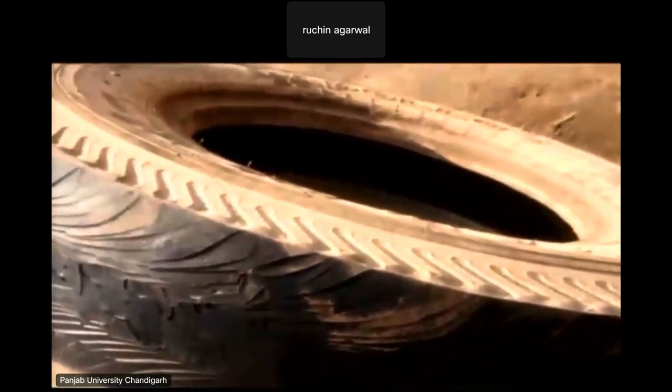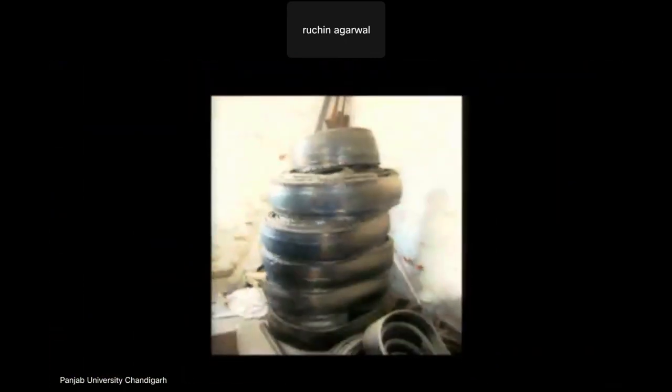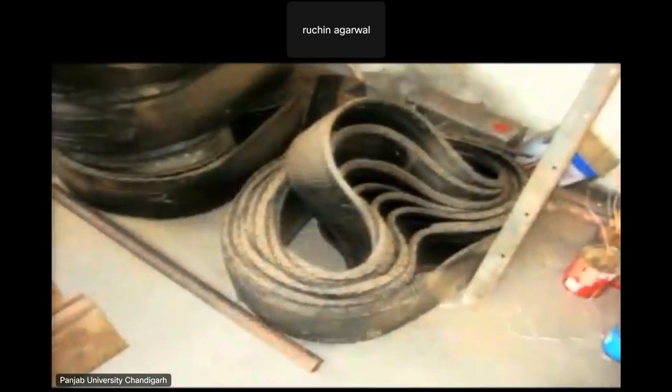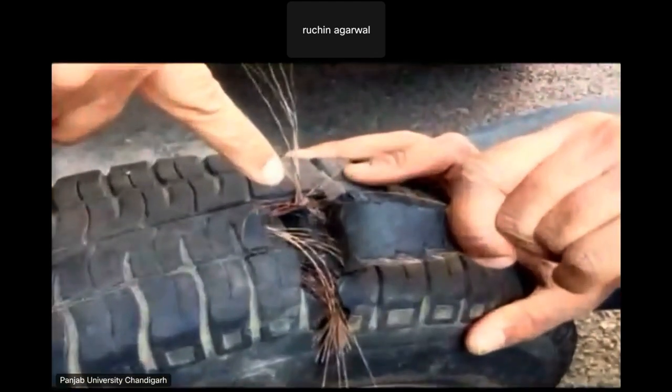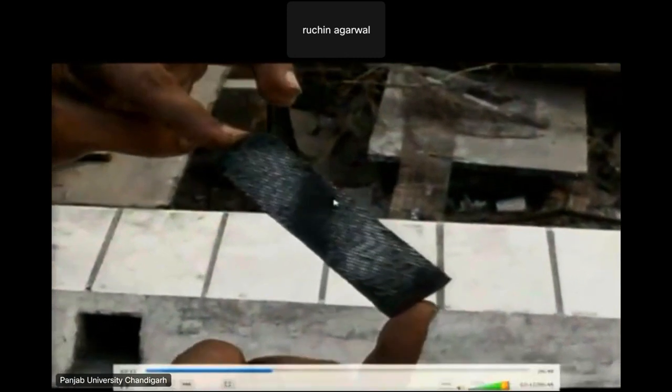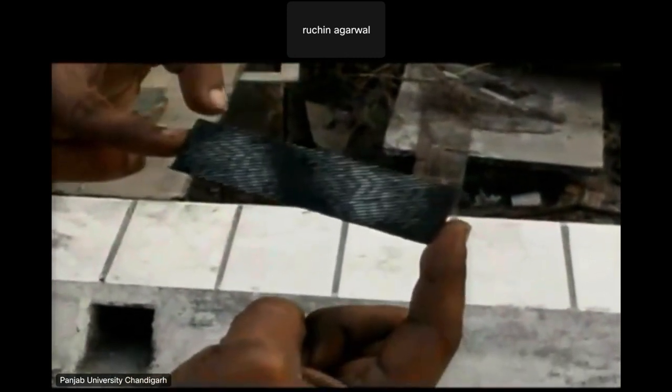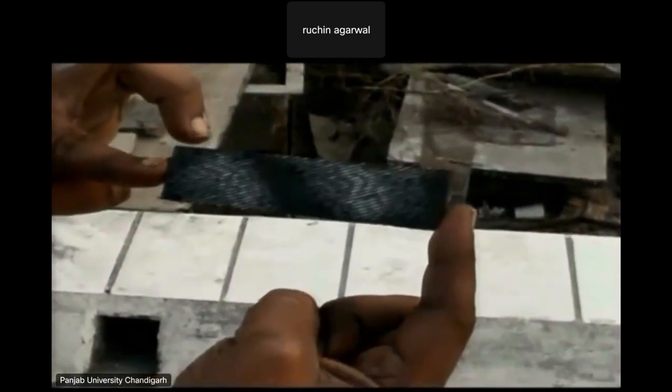These old and used rubber tires are used as viscoelastic materials because radial tires are made up of a copolymer of styrene butadiene rubber, which is a viscoelastic material. Ply, the base part of a radial tire, used for making viscoelastic energy dissipator links, has steel wires embedded diagonally in the rubber, which enhances the stability, strength, and viscoelastic property of the material.